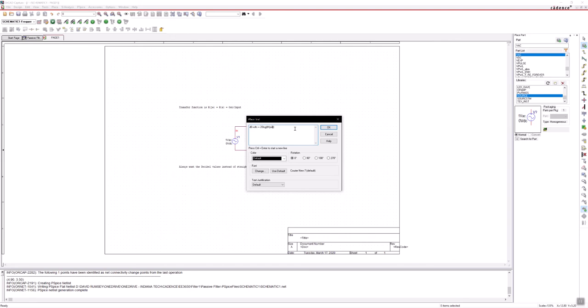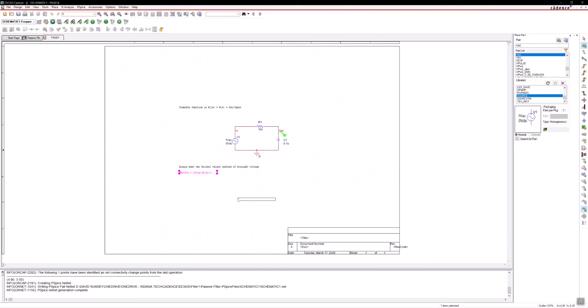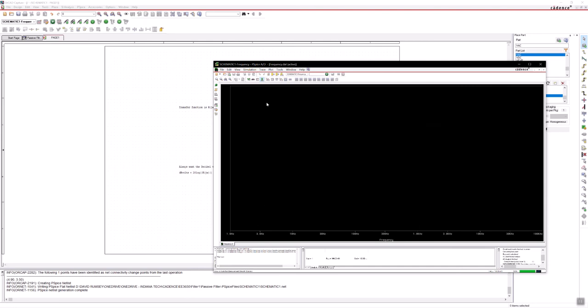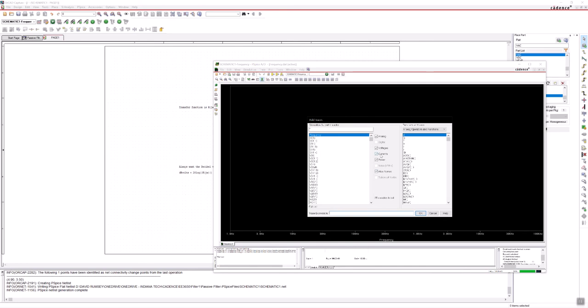And there's a reason why it's 20, which we talked about in another video to prepare for the lab. But fortunately for us, we don't actually have to sit there and do this computation. There's two ways you can do this. One here is that I'm going to just delete this trace here. And I'm going to do plot or trace. I'm going to add a trace. And I'm going to take the currents and power off. So I have this voltage output. And we know that that's my transfer function because my input is simply 1, which is nice.